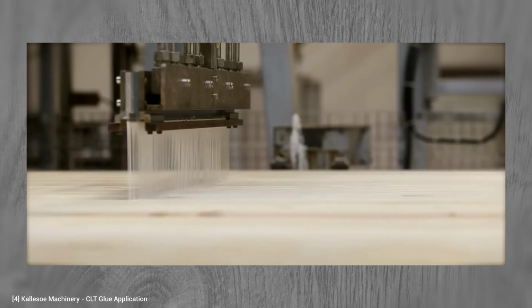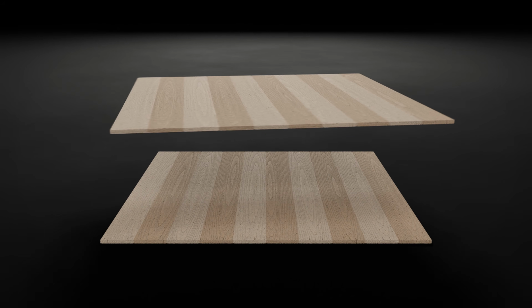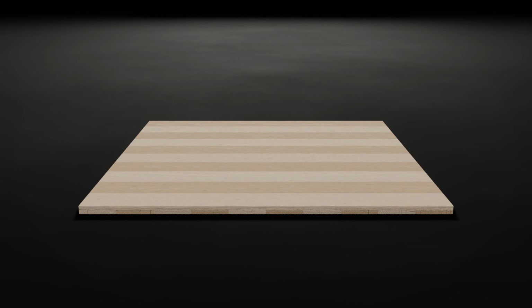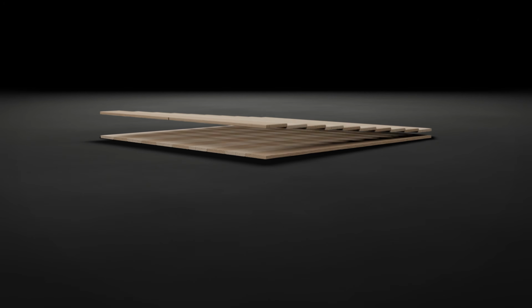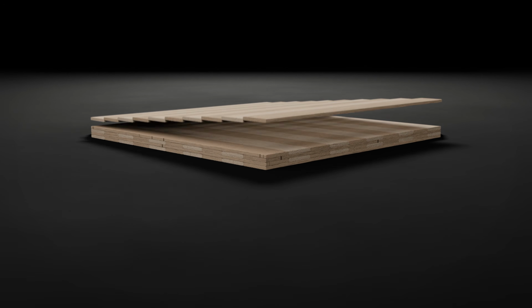Now that the planks are firmly bonded together, they get cut and shaven down to the preferred dimensions. This ensures that a full layer of wood is even and smooth. After this, an adhesive layer is applied to the layer of wood, and the second layer is applied to the first at a 90-degree rotation. This process gets repeated until a certain amount of layers is reached.